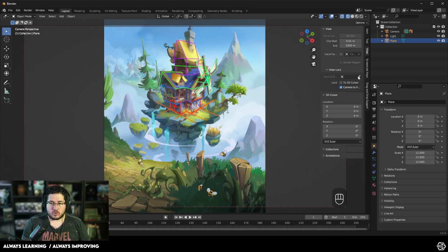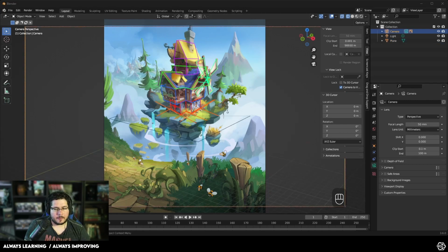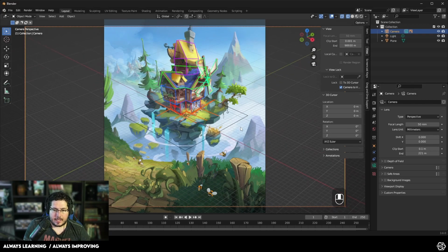And now, of course, we're going to zoom out. Yes, we're going to need to move our clipping ends and our clips right here. So I'm going to give myself one more 0 over here. There we go. And let's bring this down to 0.01. Then we need one more. Now, of course, we need to change the clipping distance because if we try to go out, we're not going to see anything. So you need to select the camera, and on the camera options, we're going to change the clipping distance. We're going to give ourselves a little bit more clipping distance, and there we go.